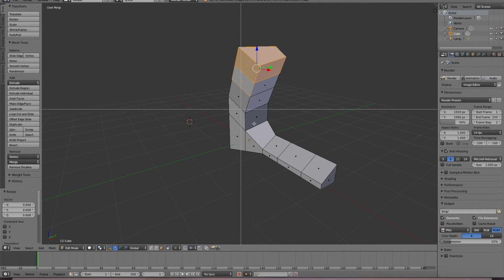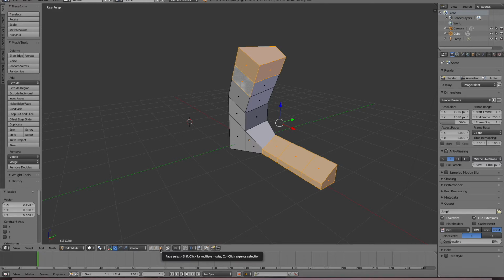If you press the B key, you will get this selection, which is a box selection, which allows you to draw a box around the areas you want to select. And you notice that we are in face mode, so we are just selecting the faces in that area. If we want to select the points, we could switch to a different mode, and now it would select the points. All right, and just to deselect, you just click a point somewhere else and it'll deselect.